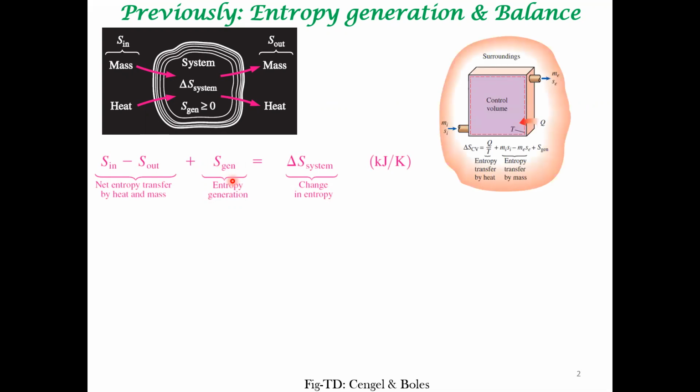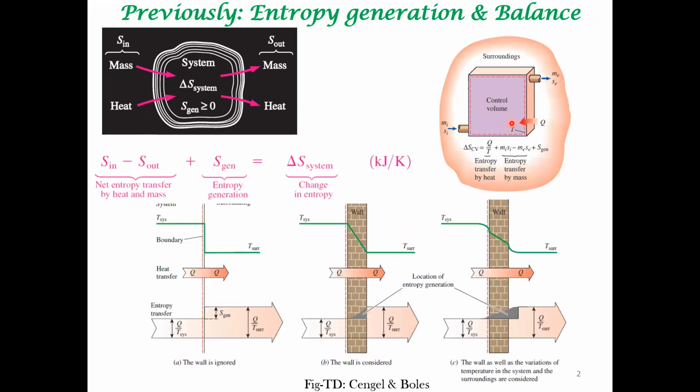However, even though it is not a conserved variable, we can write a balance equation just like we wrote for energy and mass. For example, in a closed system or in a flow system, we can associate entropy with a particular inlet and outlet stream, and entropy that comes in from the surroundings and so on. Via different case studies, we demonstrated how we can write a balance equation for entropy. A particularly good example to understand entropy generation is this simple heat transfer issue.